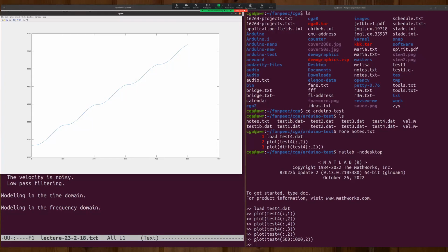So you see these two pulses, and let's say pulse A comes first. And if it's rotating the other way, pulse B comes first. So the way you figure out a direction is you keep track of which pulse comes first, and the way you keep track of speed is count the pulses.